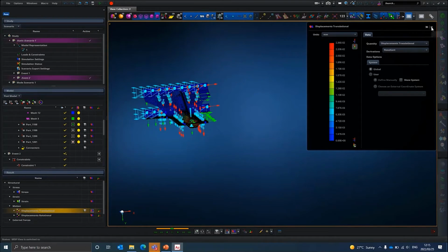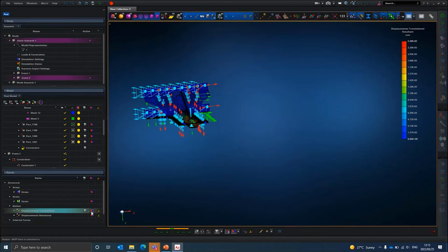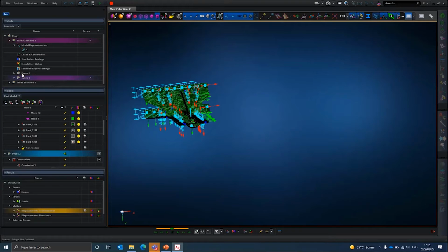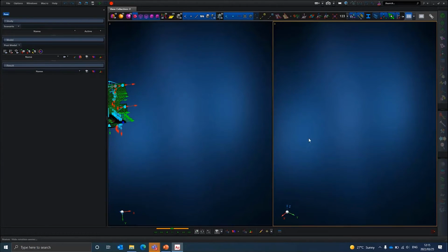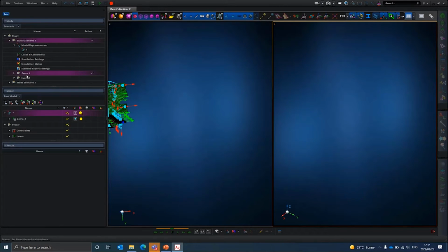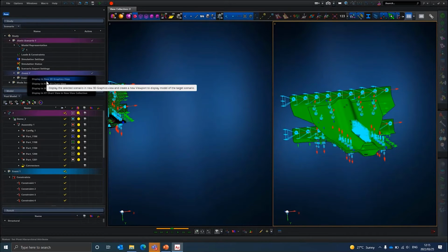Okay, so then some of the other interesting tools that are also available in the post-processing is, let me just quickly get rid of all the different things on the screen. So in this specific case, I'm only plotting results for event 2. But say, for instance, I also want to plot results for event 1 because I want to compare them. I can just right-click on it and say, please add another graphics window for me.